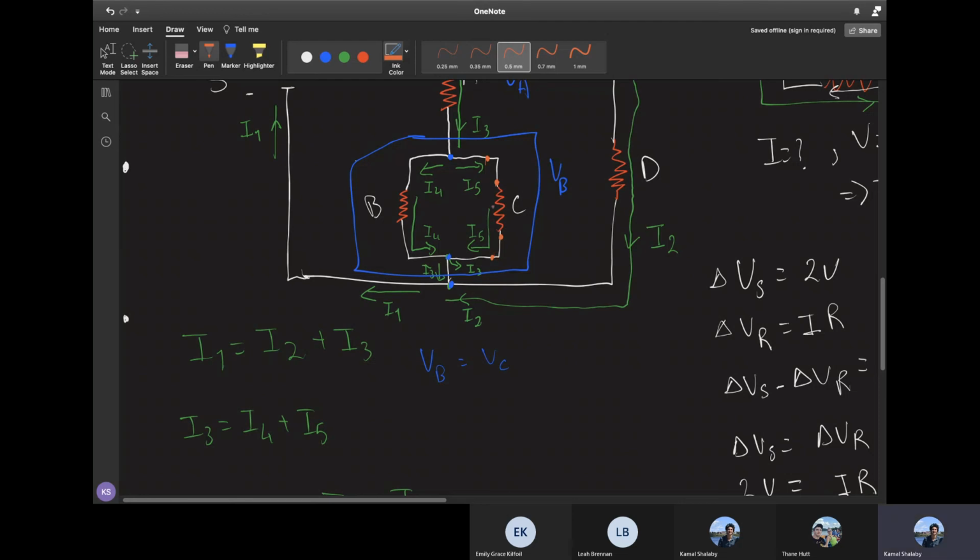It'd also be the same thing because there's no resistance in here, so it'd also be VC. What if I jumped to here? It would also be VC, right? Yep. What if we jump to this part? It would also be VC because if you're going this way, there's no resistance except for C, so it's just VC.